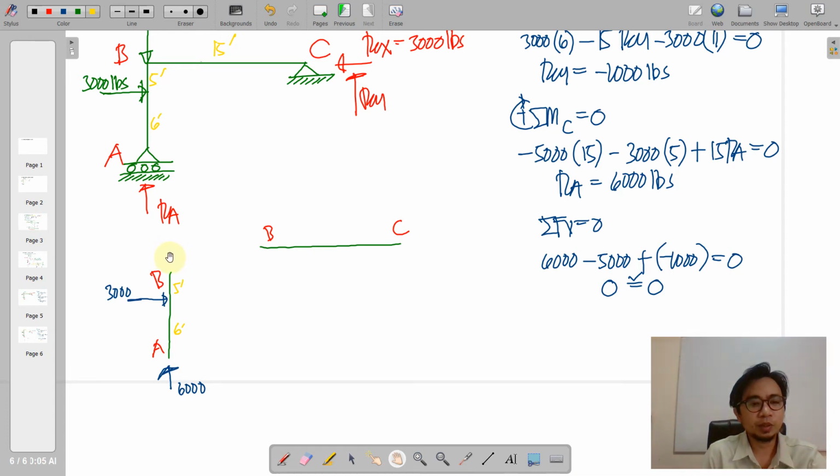So obviously, we are going to have downward 6,000 here as the shear or the reaction at B or internally. Of course, we can do it if we take an assumption of the direction, but this time your AB consists only 6,000 going upward. So it is so obvious that your internal vertical force here along B will be going downwards. That is equivalent to 6,000. Similarly, 3,000 is also rightwards here. And obviously, this will have a leftward 3,000 there. What about your moment at B?